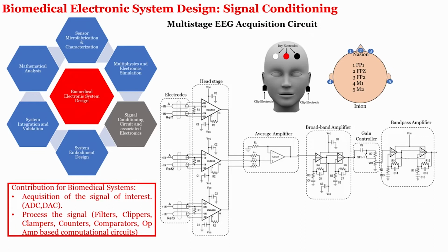So, we went into details about the electronic system, but when we talk about the electronic system, we have to also talk about the electronic module, particularly for EEG signals, since EEG signals fall in microvolts compared to millivolts of ECG. If you measure ECG, it is about millivolts. If you measure EMG, about millivolts. ECG is electrocardiography and it is from the heart. EMG is from the muscle, electromyogram. EEG is electroencephalogram, that is the brain signals.